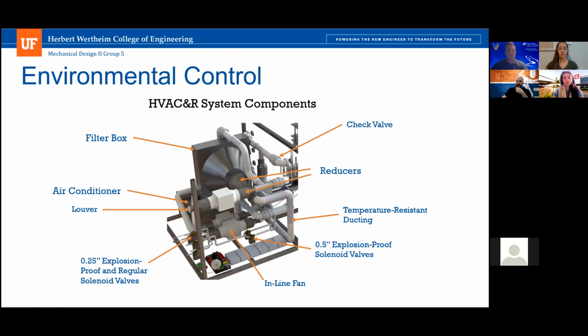Now, the HVAC system meets BSL-2 requirements by creating a sealing effect with the doors. On the doors themselves, there's a rubber that is pressed flush against the side using a door lock, as well as a filter box containing a MERV-11 pre-filter and a HEPA filter to capture biological agents and any hazardous particles that could possibly contaminate the laboratory airstream. The air that passes through the filter box will be sent out of the device and into the laboratory HVAC system.